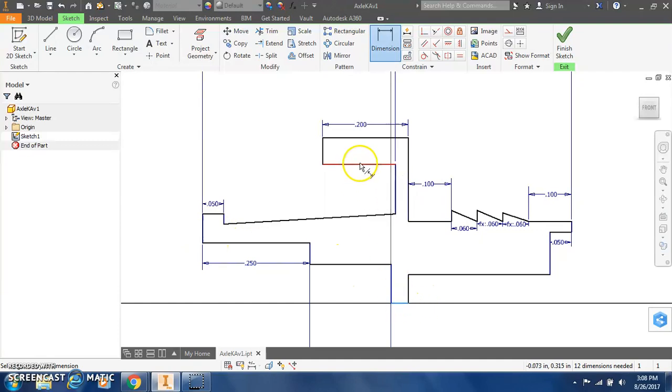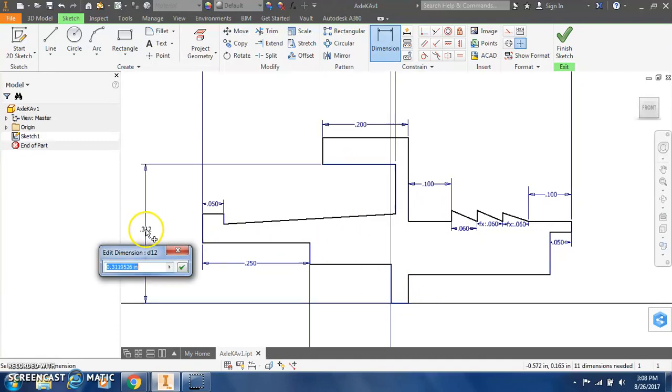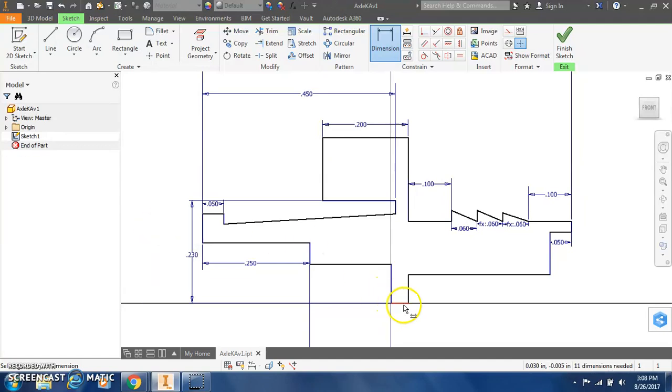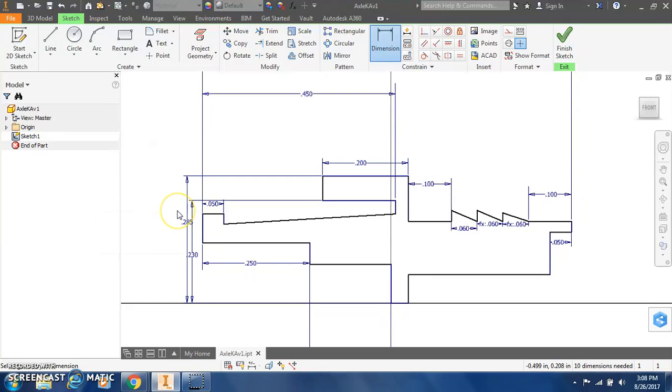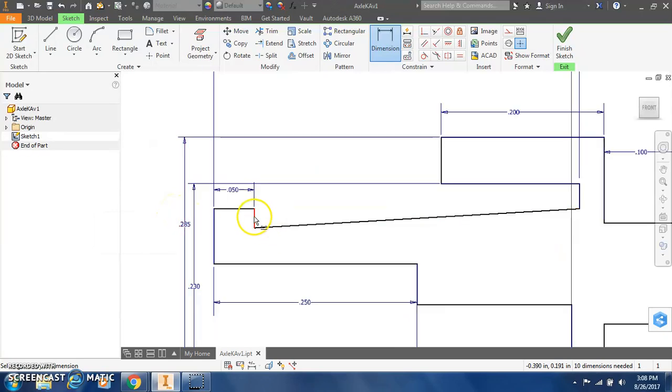the first vertical dimension, and this is 0.46 divided by 2. So instead of us doing the math on this, let's just have Inventor do it for us. And then the full height above that, if we place this, is 0.57 divided by 2. Things are starting to look aligned. This height right here is quite small. It's 0.01.